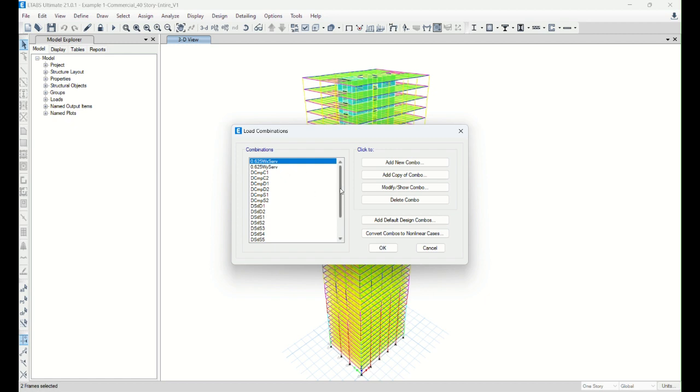But for deflections, building deflection is similar to beam deflection. We're using live load deflection, and we try to limit it to less than L over 360. Or total deflection, we're using a limit of L over 240, something like that. It's all based upon service load, which has no load factor on it.